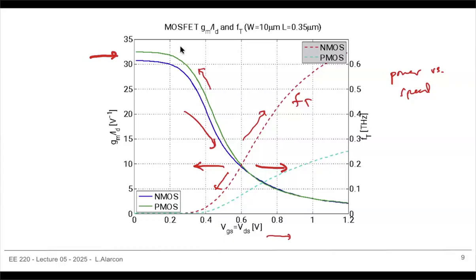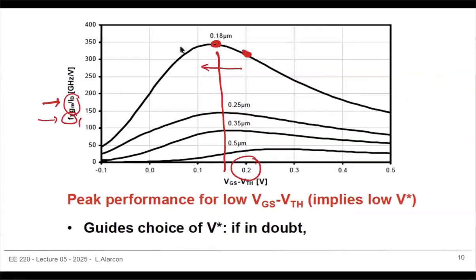It's going to depend on the application, but it's really important to understand that every time, given a transistor, I want to increase the speed, there is a corresponding power penalty for that. Hopefully this is something you've already seen in the homework, and you see that for our process, it's somewhere around a little less than 200 millivolts, just like this one, and it's several hundred gigahertz or so.